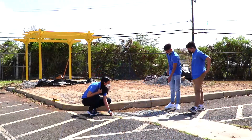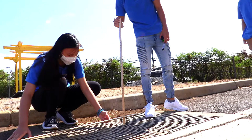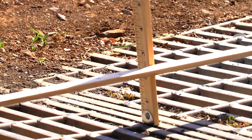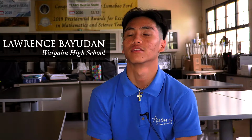My task was to walk around the campus and take measurements on the dimensions of the drains to help us understand how it affected the area around it and the water flow. After we collected the storm drain data, we also collected parking lot data, like the dimensions, to see if engineers can plug in BMPs and also double check to see if the dimensions were correct.